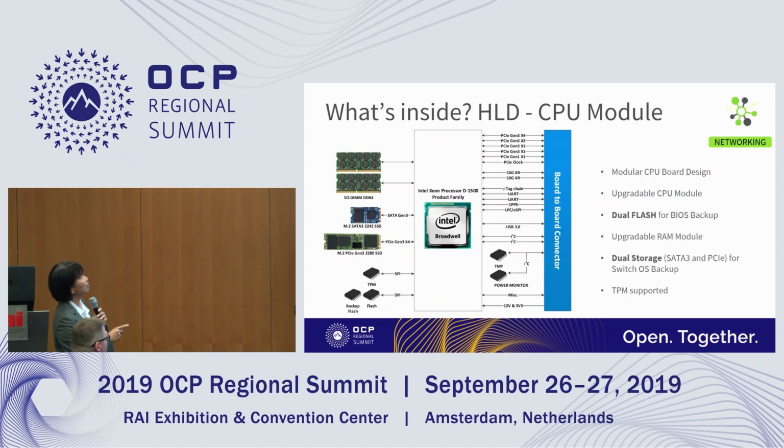Next one is our CPU module. All the CPU is in a module, with 2 DIMMs and 2 different kinds of SSD to support different requirements. And we have 2 flash devices to provide the BIOS, and there's a backup one, so if one fails, it can still run. The whole board's interfaces connect to the main board, and there is also a thermal sensor on the board and the power monitor here.